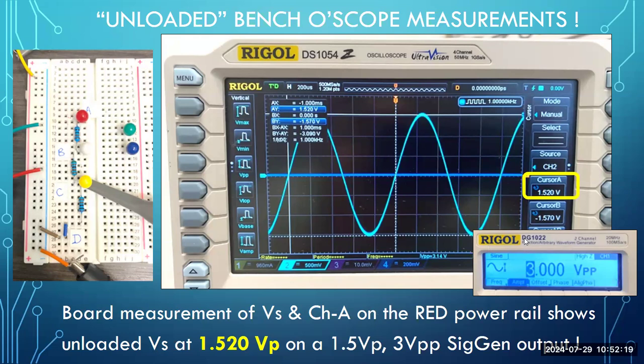So I'm using a Rigol DG1022 signal generator. I do have that set at 3-volt peak to peak, which is 1.5-volt peak. This is unloaded, as the circuitry on the board shows. There's no jumper wire between the red rail and the first resistor. So while this is unloaded, I have 1.5 volt peak coming out of this function generator, and this is reading on the oscilloscope 1.520.